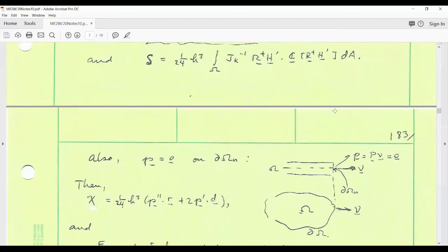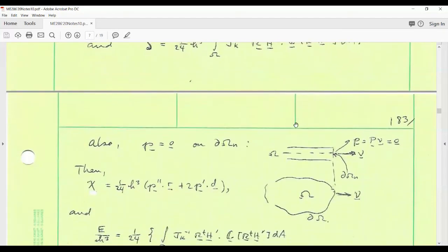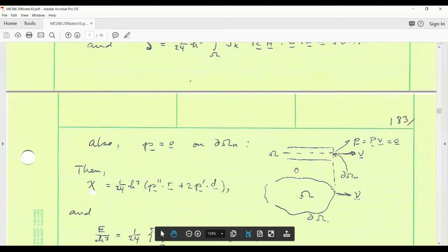As far as the load potential is concerned, well, there's no Piola stress on the midplane. So that means the traction on the edge of the midplane, that would be the midplane Piola stress times the normal to that edge, right? That would be 0. And so here's a plan view. You're looking down. Here's the normal, and so on. So with P equals 0,